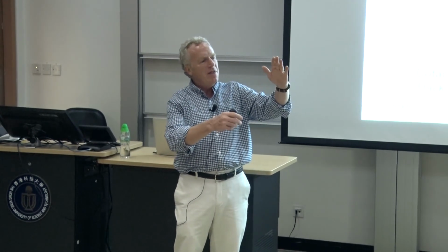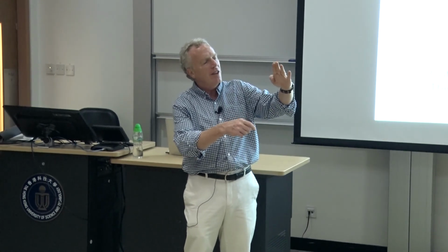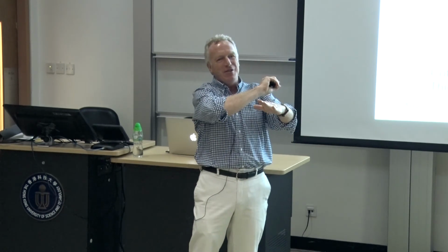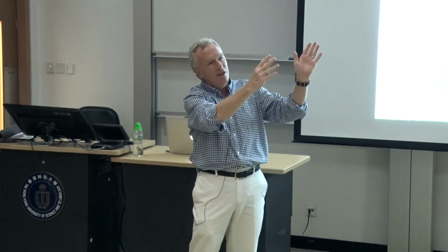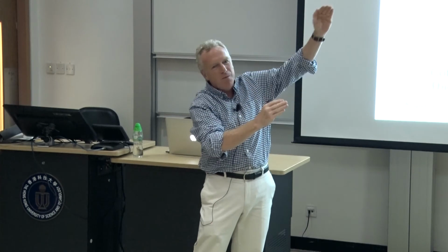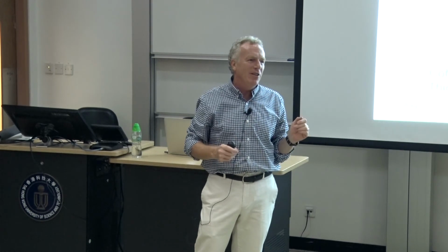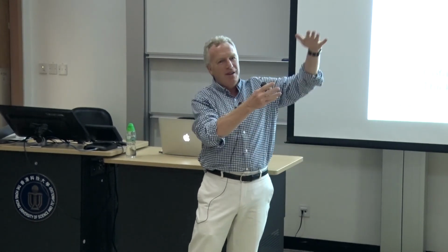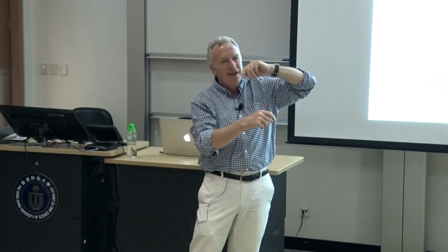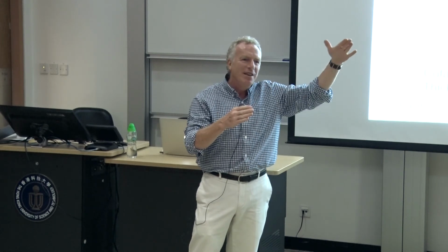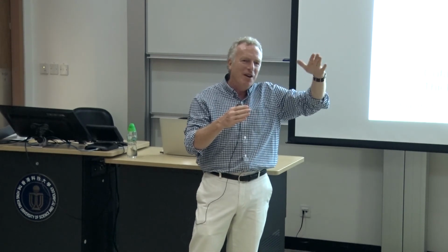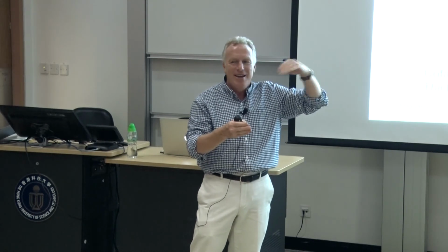But just lambda 2 equals 1, which is a perfect interface between the two phases. That's compatible with arbitrarily large volume change because the material can undergo the volume change perpendicular to the interface. But of course, as the volume change gets bigger and bigger, that kind of transformation strain gets more and more anisotropic and unrealistic. It'd be extremely hard to find a material which had such a change. Now, whether you would lose these good properties with large enough volume change, but still having lambda 2 equals 1, I don't know.